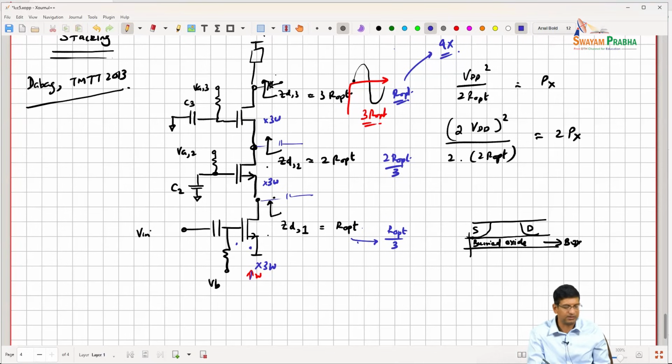There are papers, and even this paper talks about it, and more recent papers also talk about it, about creating matching or impedance shunt networks here to take out the capacitance, or creating series networks here in between to take out the impact of these parasitic capacitances, right? So all of those approaches exist, right?